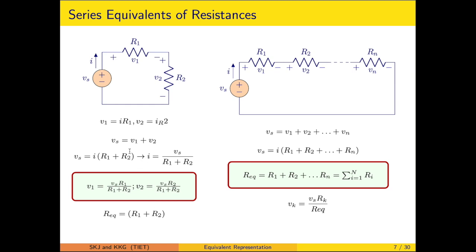The series connection acts as a voltage divider because the voltage across the individual resistor depends on the numerical value of the resistance. So you can appropriately select the resistance value if needed. However, the equivalent resistance as experienced by the source comes out to be the sum of these two resistances.